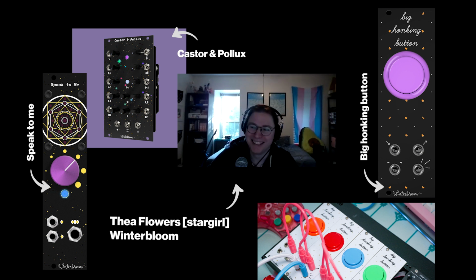No, absolutely not. It's way too small to be discrete. It has 3 ICs total. It has a TL074 as a preamp attenuator, and then it has one headphone amplifier and one speaker amplifier, and both of those are monolithic integrated. Right. Yeah, so not discrete. It doesn't need to be.